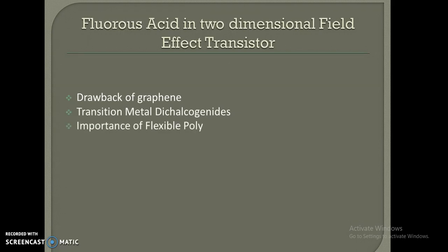Starting from it, I would like to discuss the drawback of the graphene field effect transistor: the absence of a band gap, which prevents the use of a single layer of carbon atoms in practice, since a high current ratio is required. In contrast, few-layer transition metal dichalcogenides are semiconductors, and because they are atomically thin, they are ideally suited for transistor applications. We will explore the fabrication of TMD FETs using a laser-defined ultra-thin high-K hafnium oxide. Firstly, we need to study the performance of these devices on a rigid silicon dioxide substrate.